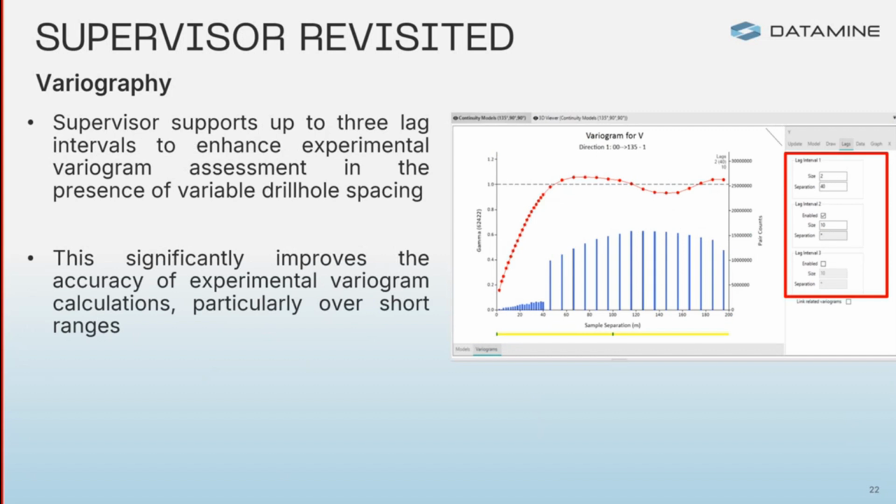And probably the latest one I want to show you is something that is not very used in practice, but it could be really handy. And it is this ability to use lag intervals in Supervisor, right? In Supervisor, we can have up to 3 lag intervals. And the idea here is that we can improve the variogram calculation when we have different drilling densities.